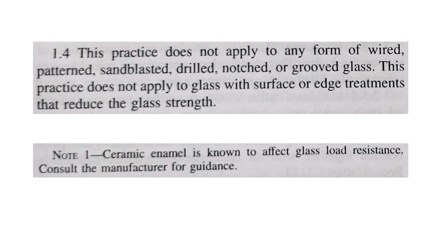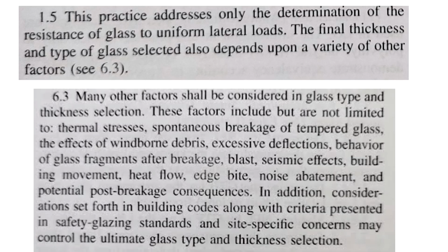This practice does not apply, paragraph 1.4, to any form of wired, patterned, sandblasted, drilled, notched, or grooved glass. This practice does not apply to glass with surface or edge treatments that reduce the glass strength. Now you have a note 1 there. It says ceramic enamel is known to affect glass load resistance. Consult the manufacturer for guidance. Okay, we can do that. 1.5, this practice addresses only the determination of the resistance of glass to uniform lateral loads. The final thickness and type of glass selected also depends upon a variety of other factors.